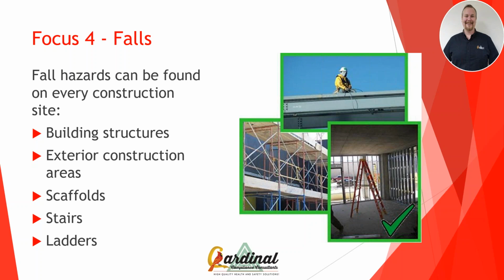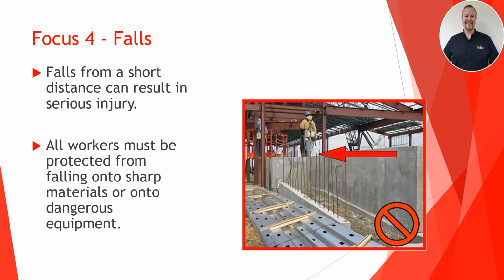They're surrounded by fall hazards daily, right? So I want you to remember, whether we're working off ladders, walking up and down stairs, working off scaffolds, or building scaffolds, in construction we have a lot of fall hazards, and they don't go away. From the beginning to the end of that project, we always have fall hazards. Now, as I mentioned with the ladder, you don't have to fall very far to get hurt.